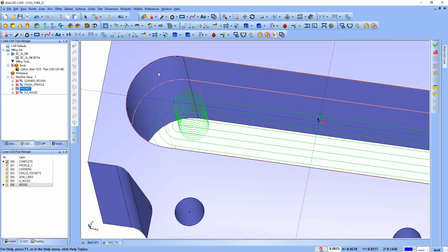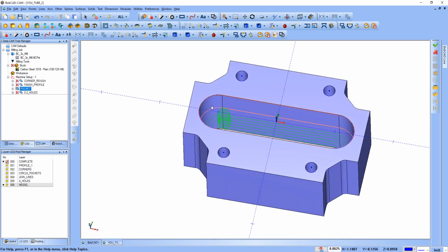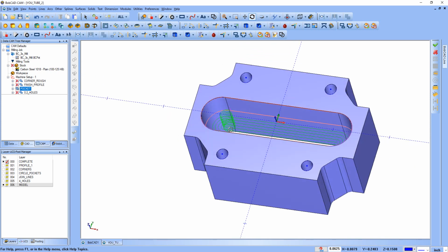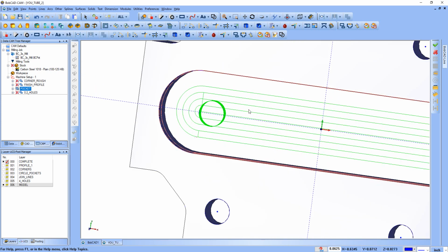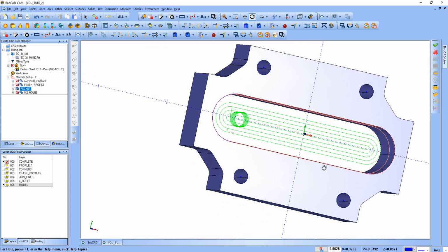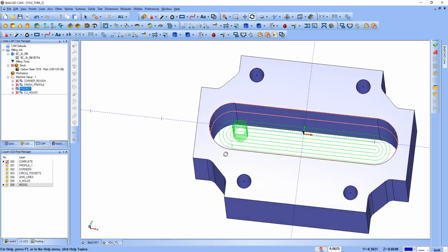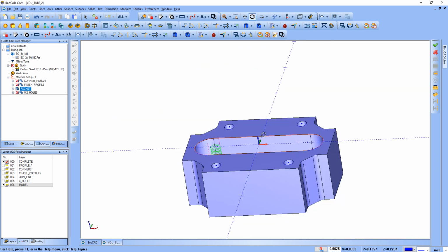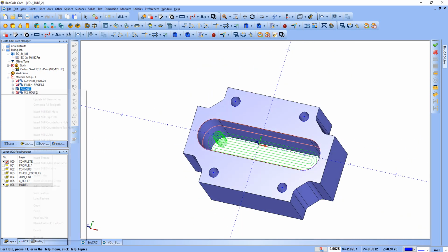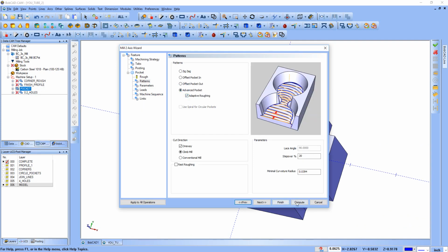So that's a basic way, and again, this may be more of an old school way. It's going to arc in like that. It's going to do that spiral. But these first cuts are going to be the full width of the cutter, if you understand what I'm saying. So at that deep of a cut, full width cutter, good chance you're going to break the cutter, or you're going to go really slow and it becomes inefficient. So that's why this is very handy.